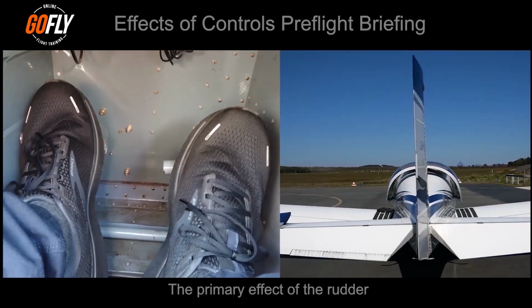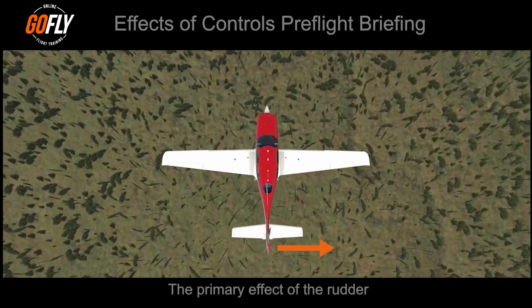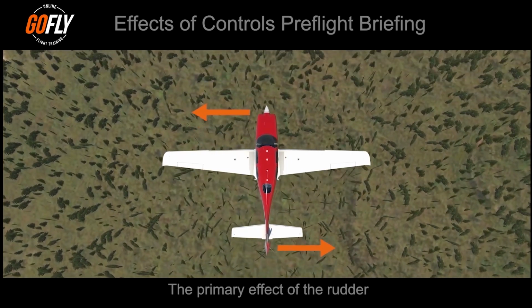When we apply pressure to the left rudder pedal, the rudder will deflect to the left and create a force to the right, and the aircraft will yaw to the left. The primary effect of the rudder is yaw.